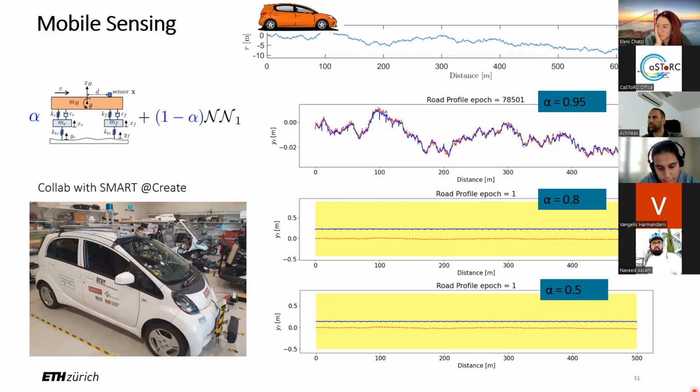monitoring can be exploited. In some cases, for example, in practical applications like concrete bridges, it might not be important to detect the crack at a very early stage because there's multiple micro cracks. It might be more important to understand when it becomes threatening to the system, and that's okay. In that case, maybe we can use macroscopic methods, as I showed, to try and deduce this. But in case where we're actually more interested in capturing the crack during its growth, and even at an earlier stage, then the appropriate type of monitoring should also change.